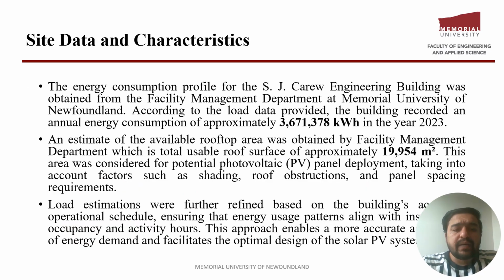As per site data and characteristics, the facility management also provided an updated estimate of the usable rooftop area, which came to about 19,954 square meters. After accounting for obstruction and shading, we aligned our load analysis with the university academic calendar to accurately reflect real energy use patterns. This helped us to optimize the system design.